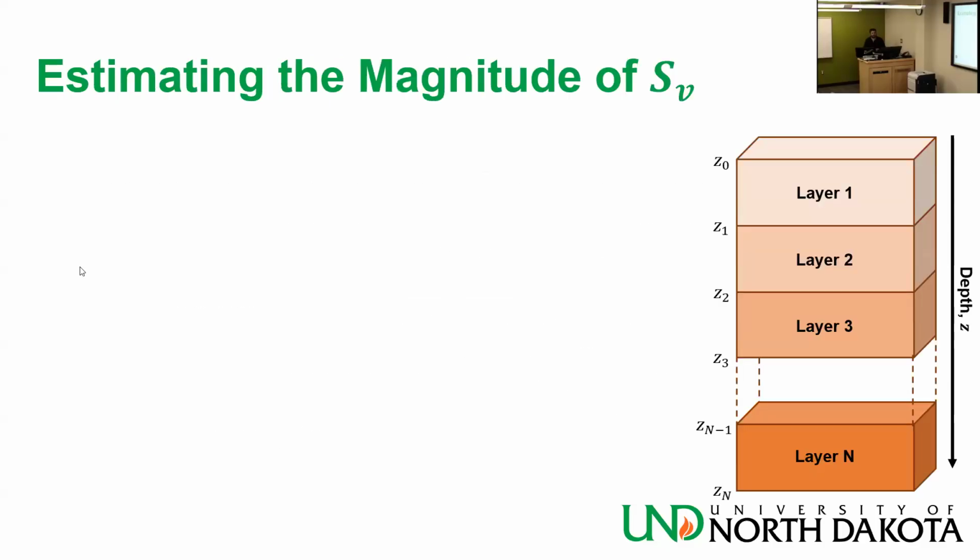Any questions? Because I'm gonna shift gears into a different subtopic. More applied, actually. So we're gonna go back to Anderson. And we said Anderson made our life simple by telling us, forget about S1, S2, S3. Let's just say one of them is very vertical, the other 2 are horizontal, and you call the vertical SV, and the horizontal, the bigger of the 2 SH max, the smaller of the 2 SH min. That's it. He made our life mathematically extremely simple.